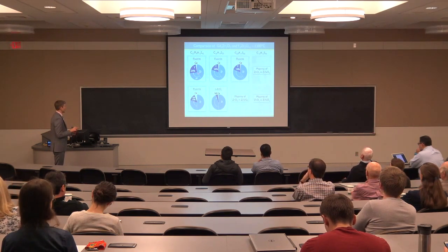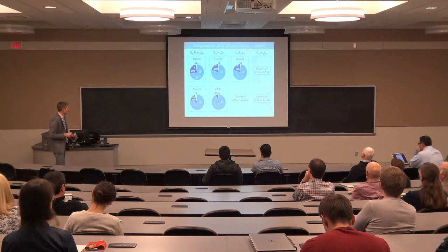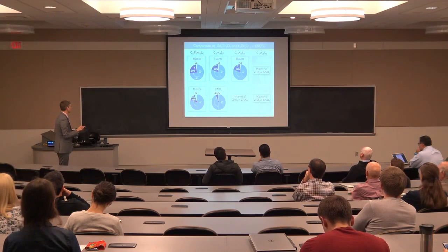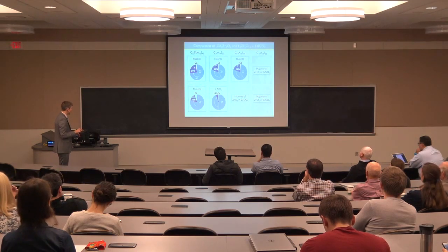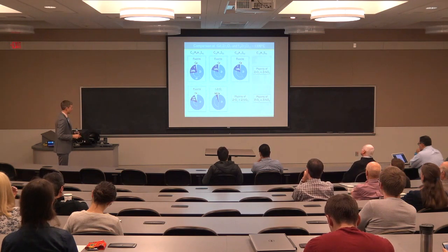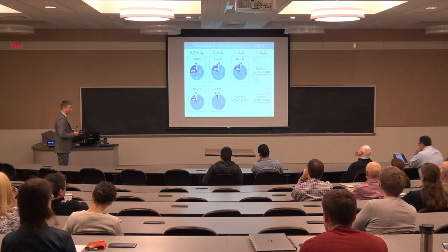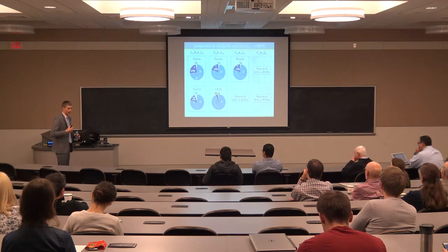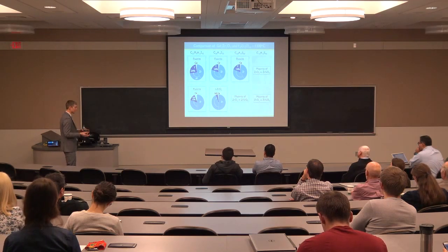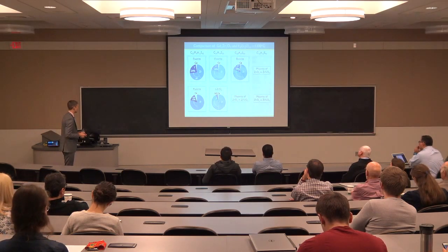However, the big difference shows up when we compare yttria and gadolinium. In the gadolinium cases, much less of the gadolinium ends up in the parasitic fluoride phases, and it's only in the really calcium-rich systems that the fluoride shows up at all. Otherwise, we basically get pure zirconia back or we form zircon. And this turns out to be an important factor in determining the difference between the behavior of the different rare earth systems.